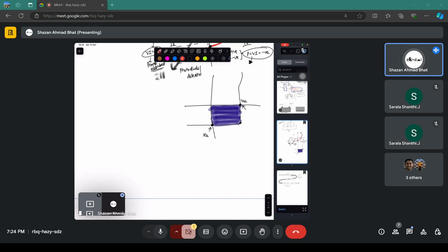But when you draw the realistic curve, this black curve is basically the ideal. When you see the ideal solar cell curve, you have something like this. So this is the real. So you want to match this real curve more and more to the ideal curve, so that you can have the VOC and ISC product maximum. And that's what you will be seeing in the solar cells.